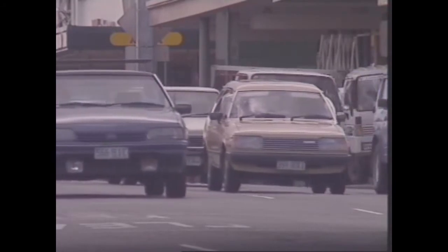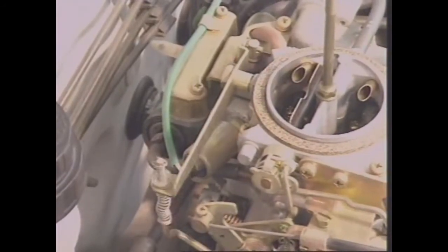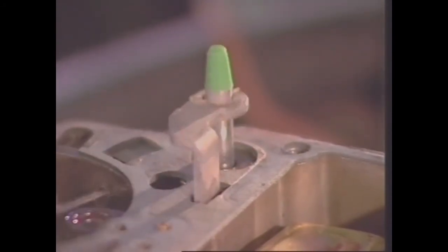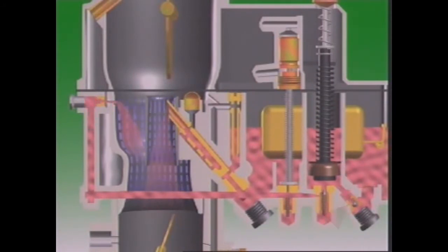Extra fuel is also needed for accelerating. Suddenly opening the throttle increases the airflow, but fuel cannot flow from the discharge nozzle quickly enough to match it. An extra jet of fuel is needed. Depressing the pedal compresses a duration spring that exerts a force on the plunger of a small plunger pump. This pressurizes fuel below the plunger and closes off the inlet valve. Fuel flows through a bypass jet and enters the airstream from a discharge nozzle above the venturi. The duration spring extends the time for delivering the fuel.